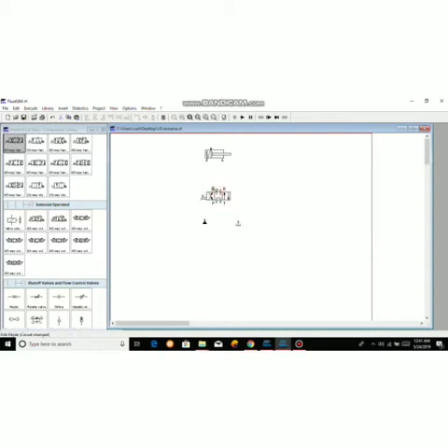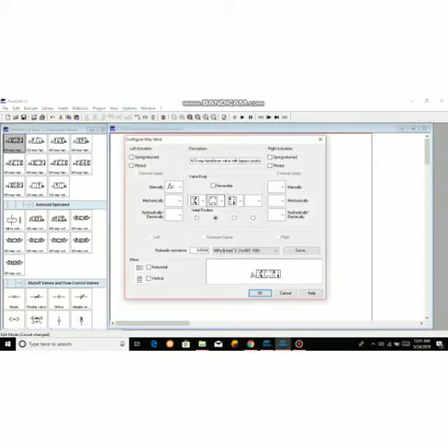So attach A to this one solenoid, B to this one solenoid, and P to the pump unit and T to the tank. Then double click, and change this to the right way, and the same way here. So disable this one. We want the spring return to be electrical, so the right way is already electrical too.